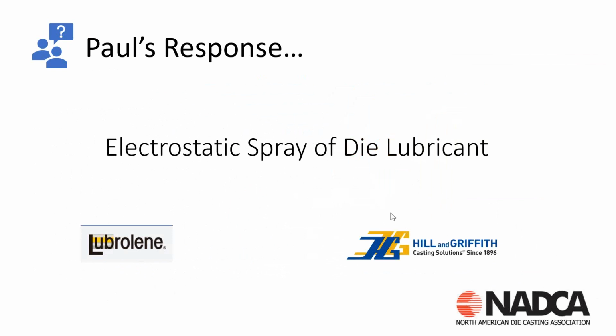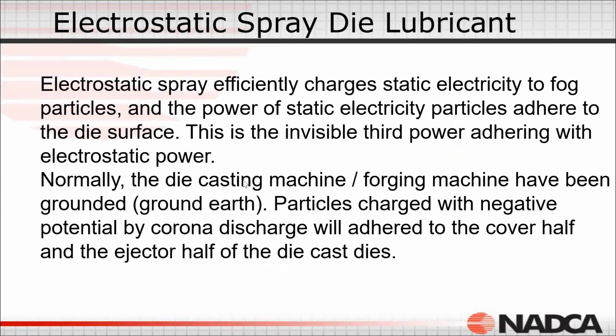Hill & Griffiths is a US company, and they have a lube system, and they have experience in dry lube, in electrostatic spray. Luberline, I don't think they're domestic, but they do have a presence here in the United States, and they also have a material for electrostatic spray. So electrostatic spray is where it efficiently charges the spray, and then the tooling is typically grounded, and those charged particles adhere to the tooling.